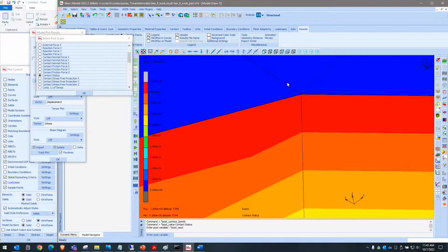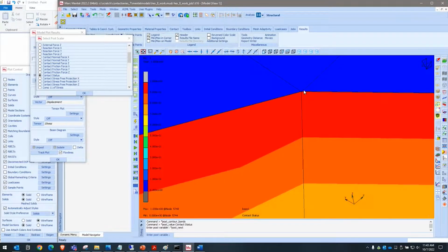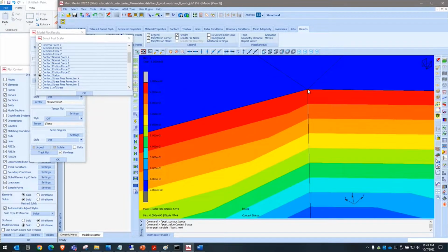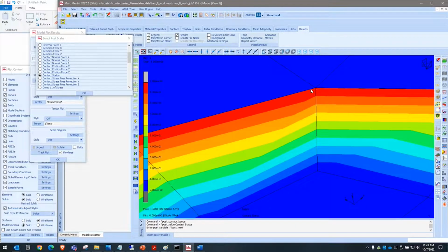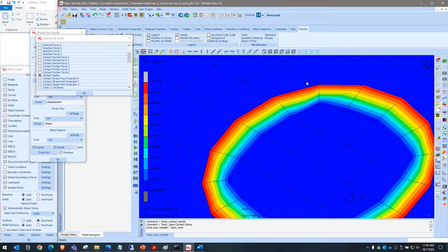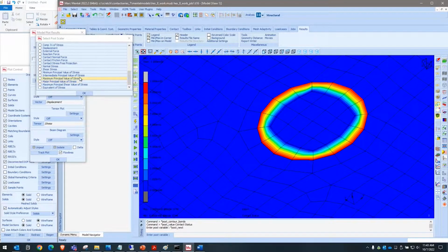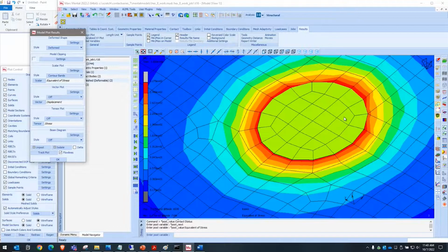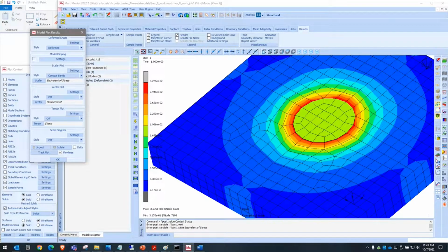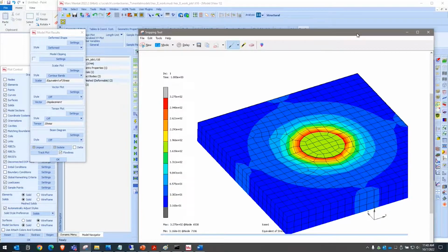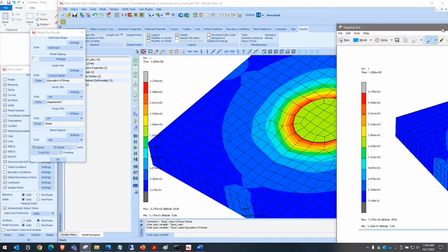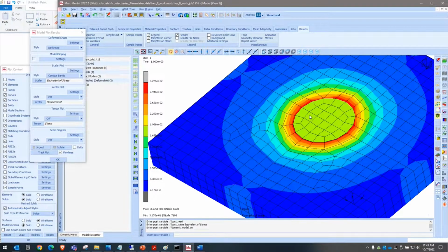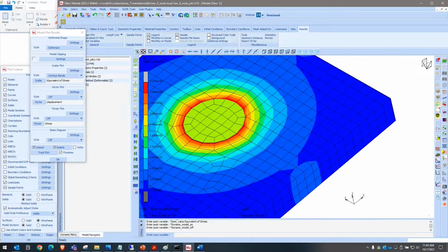So if I go to the next step, you'll see that it doesn't necessarily look like it's perfectly in contact, but the reason for that is this slight sideways offset and it makes contact against that spline. Okay, so if I now look at the stress state, very similar to before. Let's take this again, look at the numbers. So the maximum is exactly the same, the minimum slight change, the pattern not exactly the same, but very close to the same.